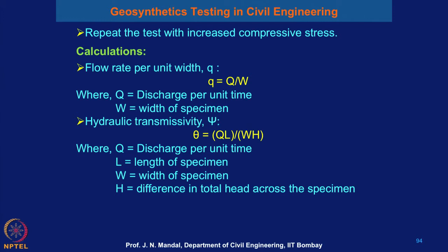So, if you know the quantity of water, you know the length of the specimen, and equally you know the width of the specimen and the difference in the hydraulic head of the specimen, then you can calculate the hydraulic transmittivity of the geosynthetic material.